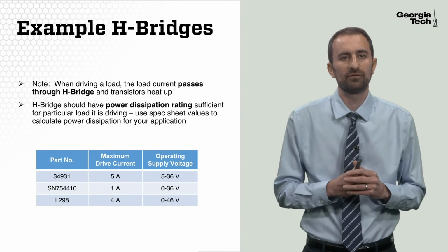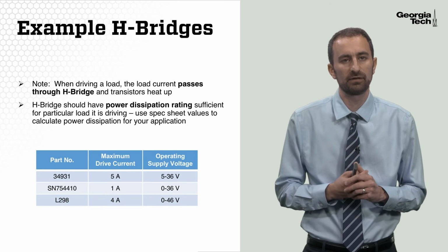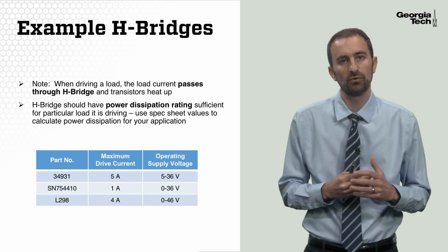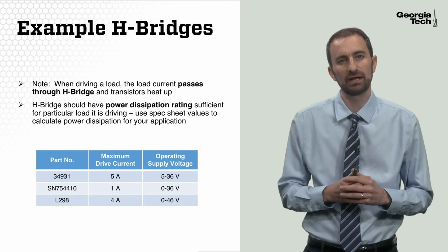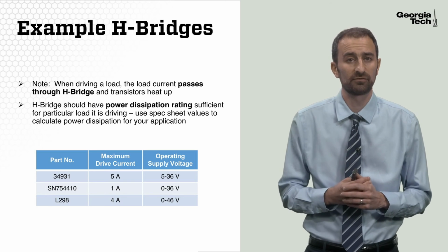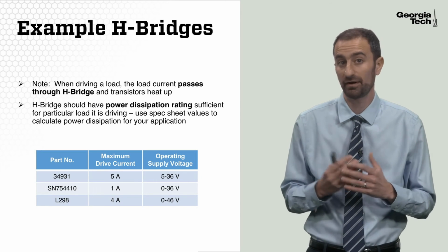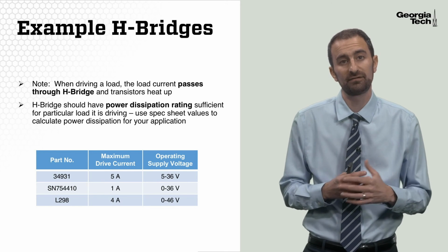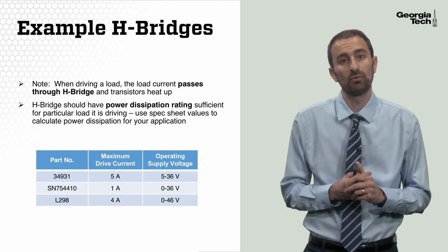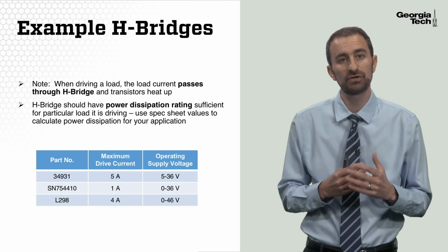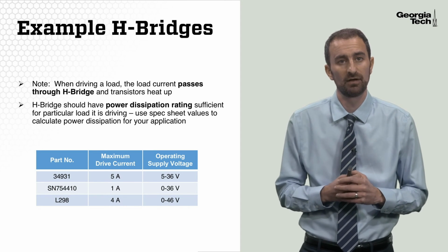Finally, let's look at some example H-bridge integrated circuits. First, before looking at some of the specifications, I want to note that when we drive a load using an H-bridge, the load current passes through the H-bridge. So not only does it pass through the motor, but it also passes through the H-bridge, and that's going to cause those transistors to heat up. So we should make sure that the H-bridge has a sufficient power dissipation rating for the load that we're